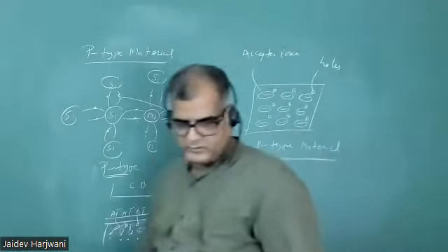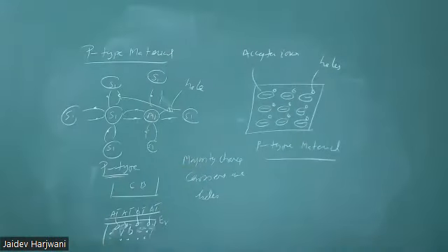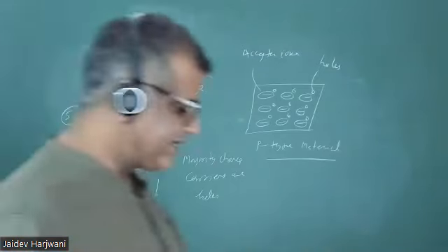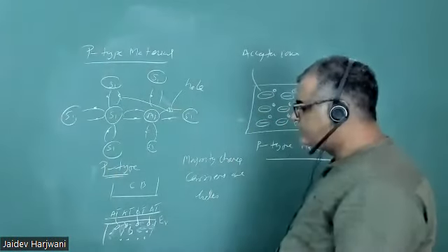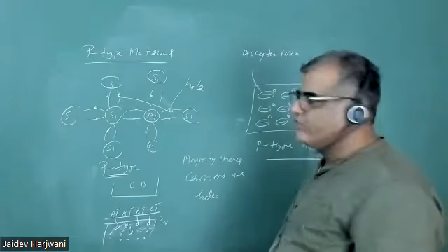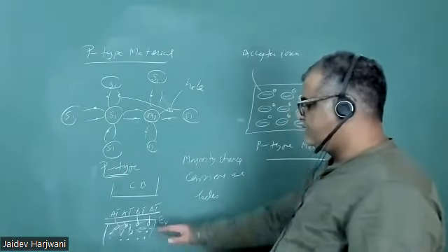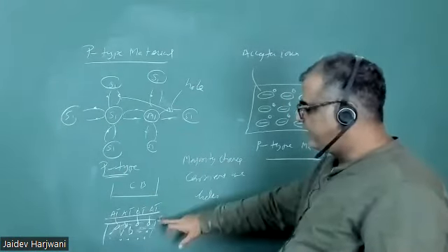सर तो इसमें कंडक्शन कैसे हो रहा है? कंडक्शन बैंड में तो गया ही नहीं सर. वैलेंस बैंड में होल्स मूव कर रहे हैं. तो कंडक्शन हो गया. इलेक्ट्रॉन के कारण नहीं हो रहा, होल्स के कारण हो रहा है. कनेक्टिविटी होल्स के कारण है. होल्स को एक एनर्जी लेवल मिल गया ना मूव करने के लिए, इधर.